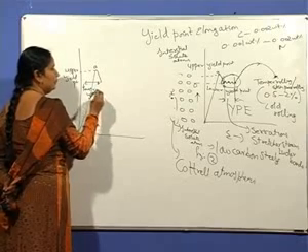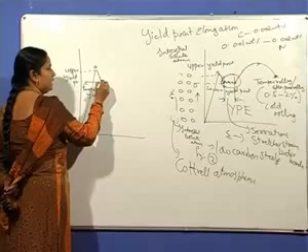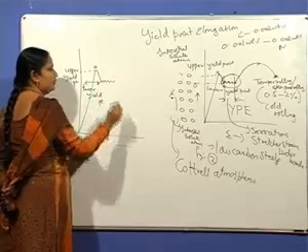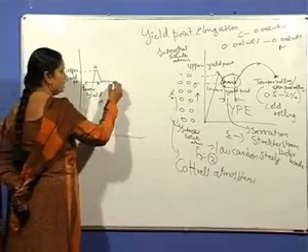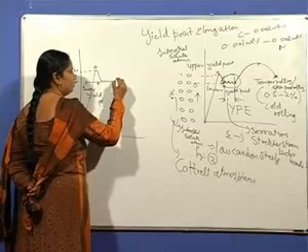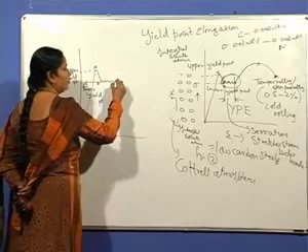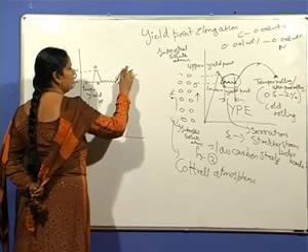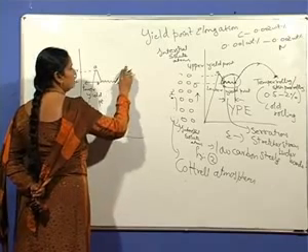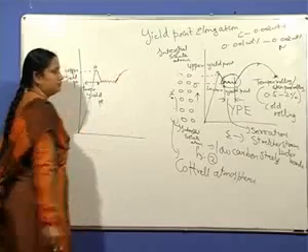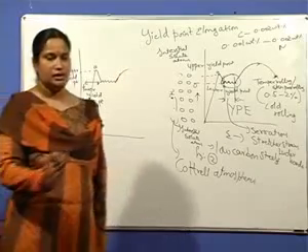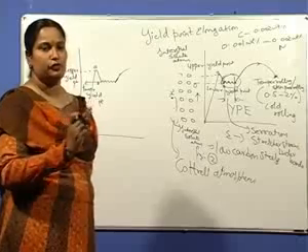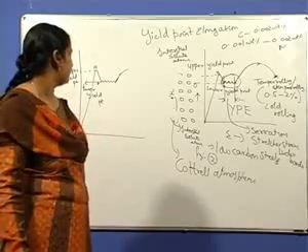This is the lower yield point. And at B, at constant stress, the material undergoes yielding. Again, the material follows the normal stress strain curve, because the dislocations are torn out from the Cottrell atmospheres.